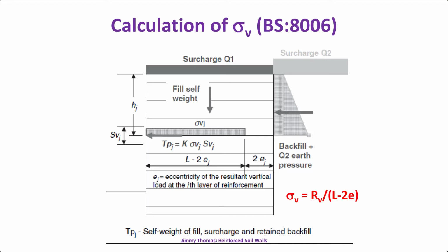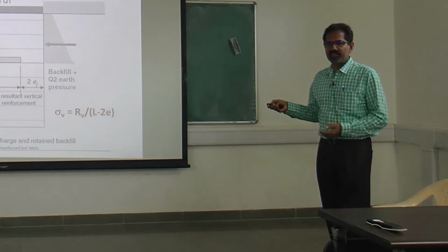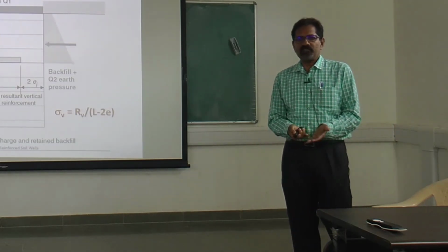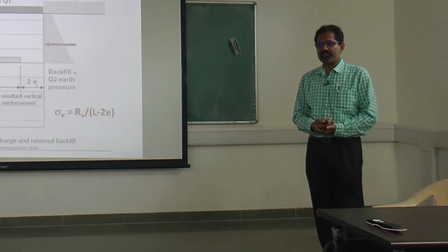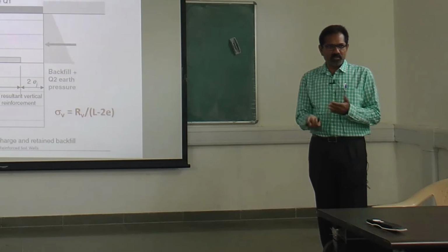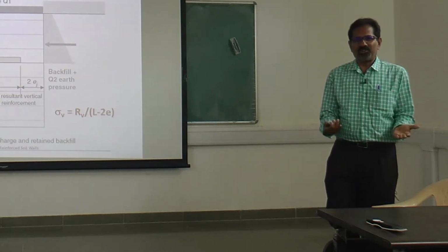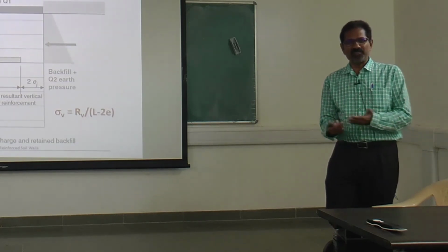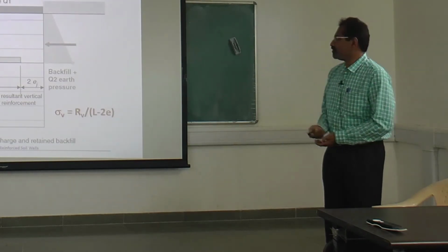Obviously this is going to give me more vertical stress and more tension. The difference could be something like 20%, 25% more. That is why the BS will predict more reinforcement tensions. If you design with FHWA, it will be more economical. So it is the difference between codes. We cannot say the other is wrong or this is more right. Different countries, different experience, different approach, that's all.